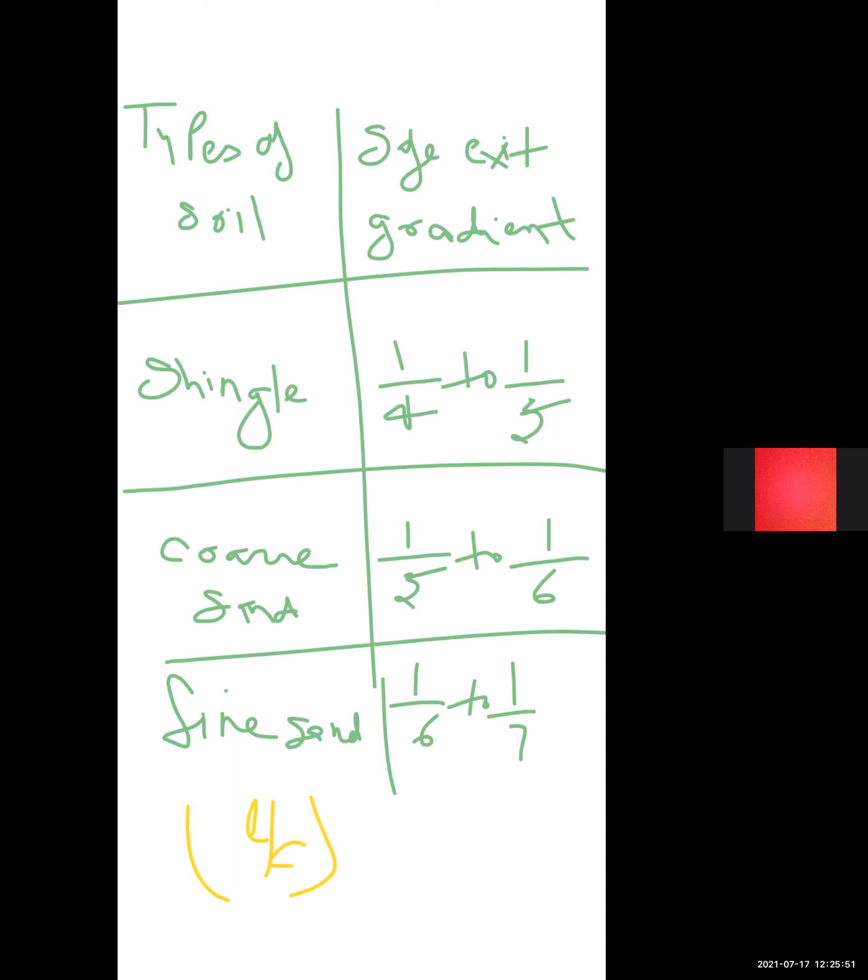So a weir or barrage may fail not only due to seepage, that is the subsurface flow, as stated by Bligh, but it may also fail due to surface flow. When flood water flows over the weir crest, it may cause scour, dynamic action, and in addition will cause uplift pressure in the jump trough, if a hydraulic jump forms at the downstream section.